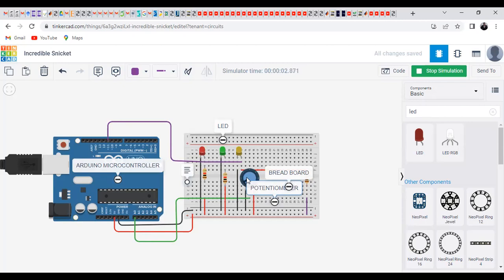So thank you very much for listening to me. In this example, we've looked at how we can use Arduino microcontroller to read analog input signal, convert that value to PWM form, and then use analogWrite function to send out the PWM value. This kind of problems or scenarios are common in the industry, especially in scenarios where we want to run motors using digital control means.